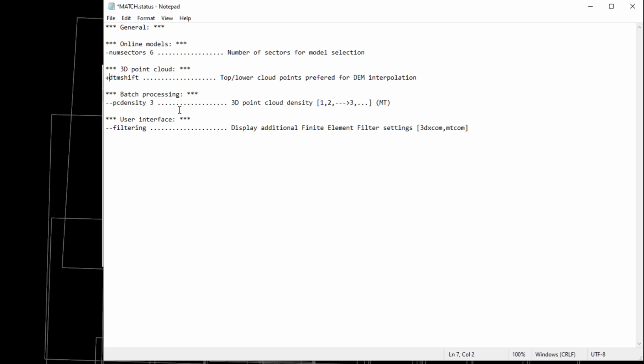By using the terrain type extreme later on, we automatically make our cells smaller, and therefore we can be more flexible with specific small objects that are close to each other, and therefore still keep the DSM as good as possible.